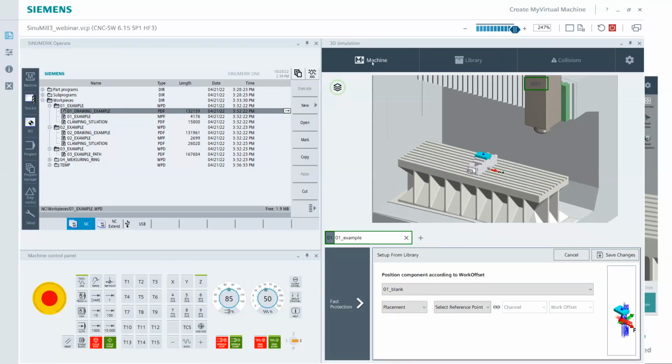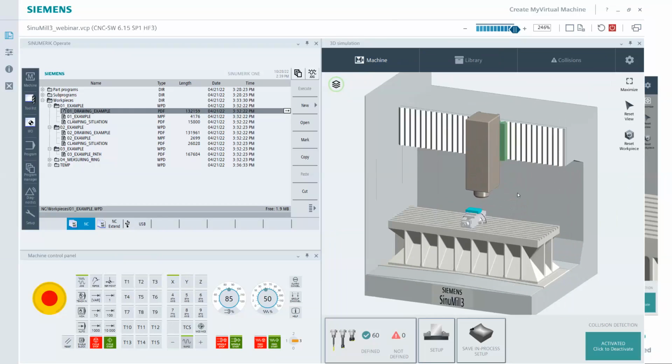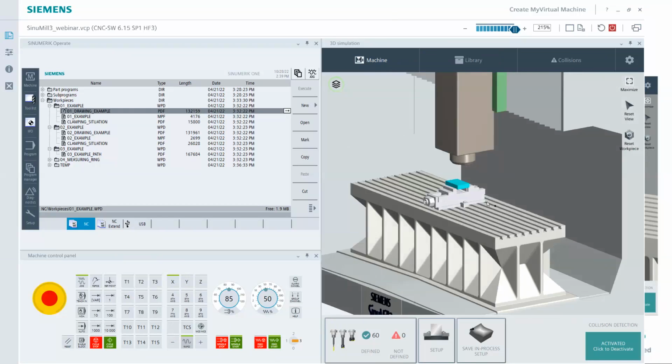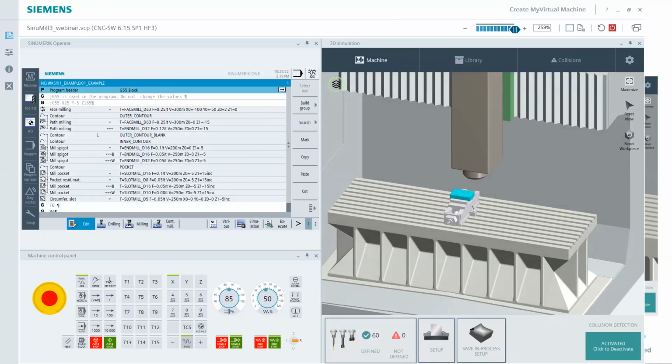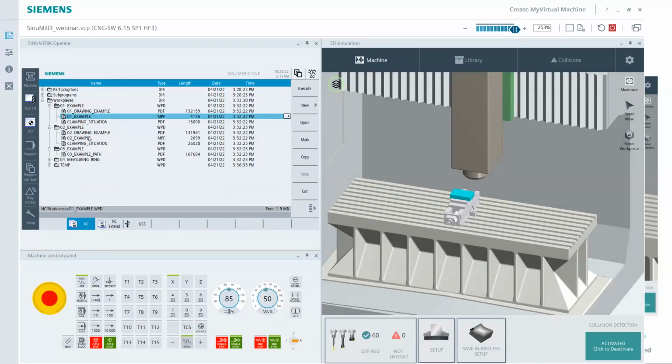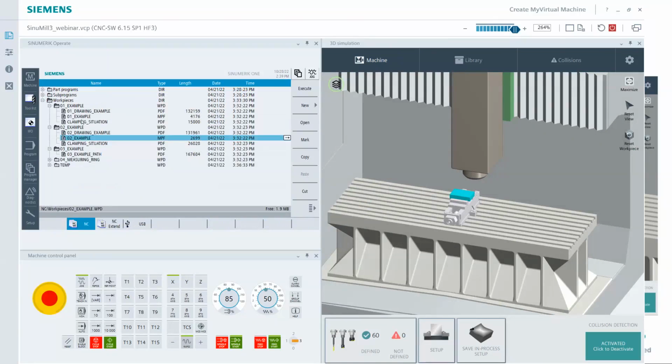So now click the machine button again. This lower window is going to close. And now I'm physically back in the running area of the machine. All right, I can start to jog it around. So once I load the part and I have it sitting on the table, as long as I haven't changed anything, I can load the machine. They're using G55, so be careful with that. When you look at your different examples, whatever work coordinates that one's using, 56 they were using, you may want to reserve them or at least write the values down.